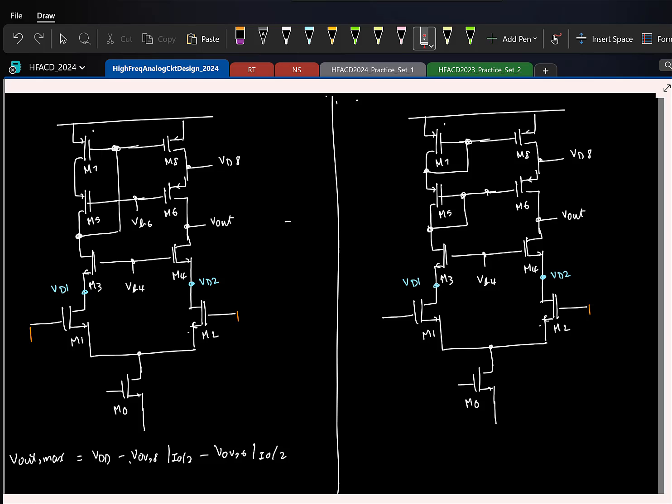What will change? Okay, think, right? Only change we have made is in this portion. In all our small signal calculations, be it the short circuit GM or finding output resistance, we essentially used only two information about this portion. Number one is the fact that this is a current mirror, so any current flow that gets mirrored. Same thing is happening in both of them.